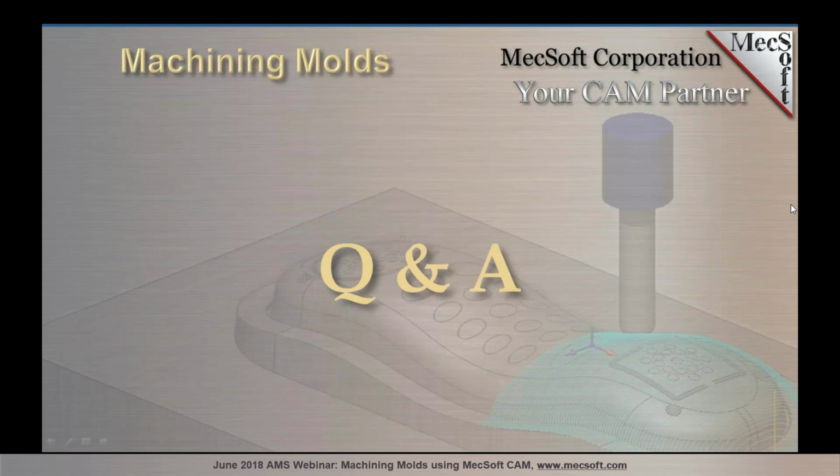One in particular that's going to help you in cutting molds is if you go to our blog and look up machining accuracy. It'll give you a lot of the different places you can go to check your accuracy, make sure that you're outputting the decimal point places of accuracy that you need for your particular application, both in the CAD system and in the toolpath itself, and then also in the post-processor, and then also in your controller, just to make sure that everything's getting the amount of accuracy that you require. That's all I wanted to add.